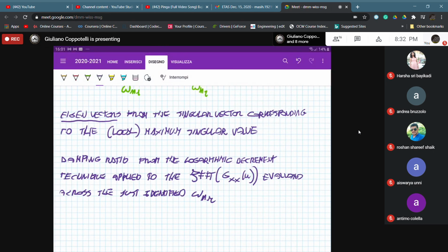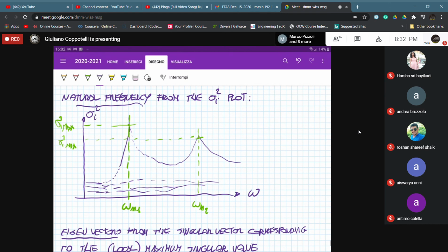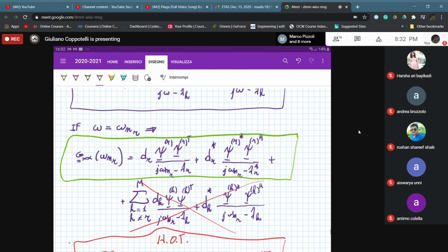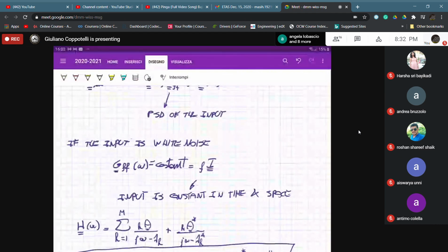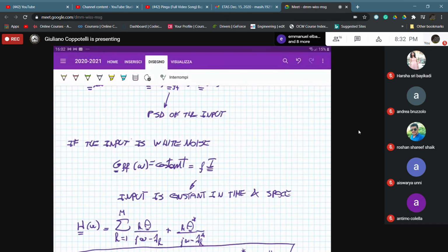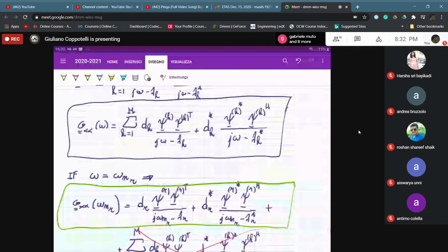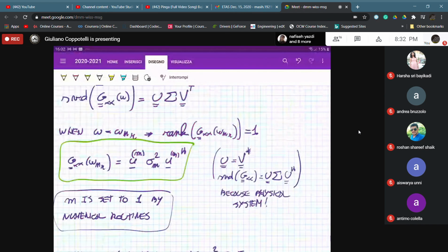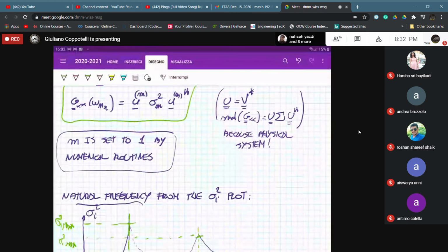This frequency domain decomposition method is based once again on a random stochastic excitation, white noise input excitation, because otherwise we can't do that much. Of course, there are some improvements to this method by taking into account other factors, but it works very well. And once again, this operational modal analysis called frequency domain decomposition has been used many times. I use it many times in flight tests for flutter certification in order to track, for example, the damping ratio over the 12 dB g plot that is typical in the flutter characterization using flight tests.